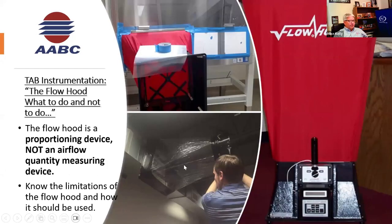Here's the proper tools for the jobs. Here we see a biological safety cabinet taped off with blue tape and plastic and a flow hood. Here we have another flow hood with a clear skirt. I hope it's blanked off at the bottom there on that outlet. Remember, a flow hood is a proportioning device. It's not an airflow quantity measuring device of accuracy.